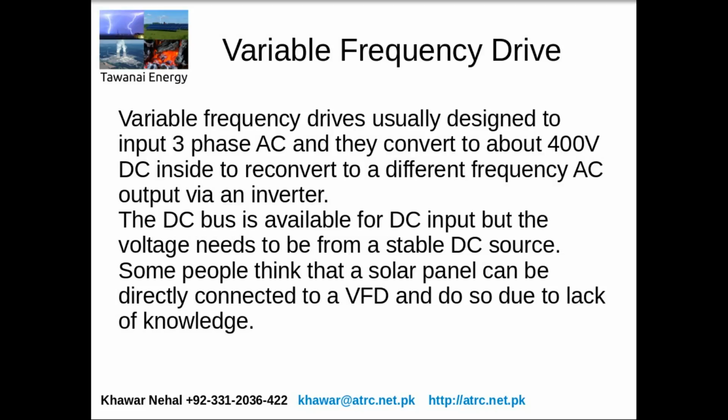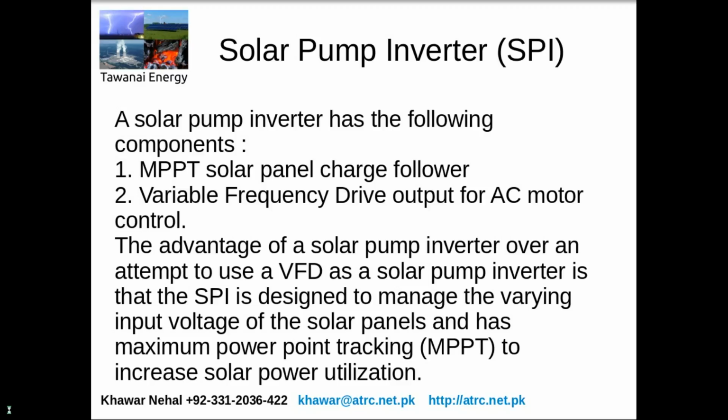The DC bus, which is the middle portion of the variable frequency drive, has terminals which are available in case you have a huge DC power supply available to run the VFDs, but it requires and is designed to have a stable voltage. Some people connect solar panels to the terminals of the VFD DC bus, and they do that due to lack of knowledge about VFDs.